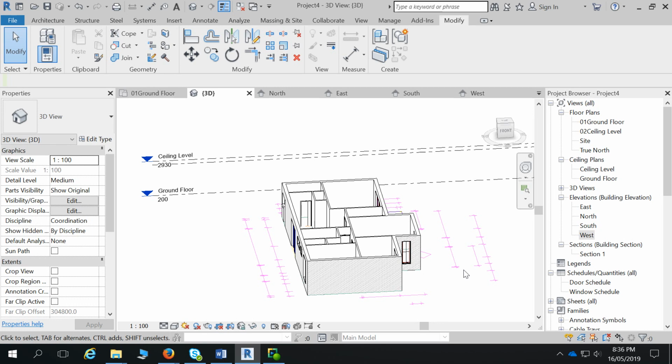No, so it's whatever size. The head height's a consistent one, and then the window sizes change, sort of thing. You know what I mean? Does it change on the downward side? So you want to fix this one, the top, for all the windows around the house, and the bottom side will change. Yeah. So if you align it to that window reference level, and it's 1200 high, it'll be whatever towards the ground.